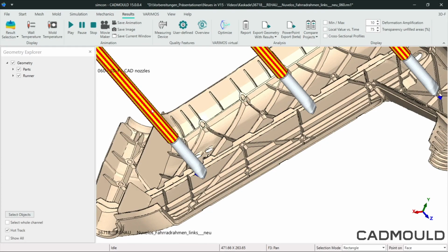Additionally, I'd like to show you another example where the hot runners were created with runner objects. In some cases, it is better to create hot runners with their objects, especially if it's not possible to do a good calculation with hydraulic diameters. For example, we have those quite flat hot nozzles where it is better to have objects.